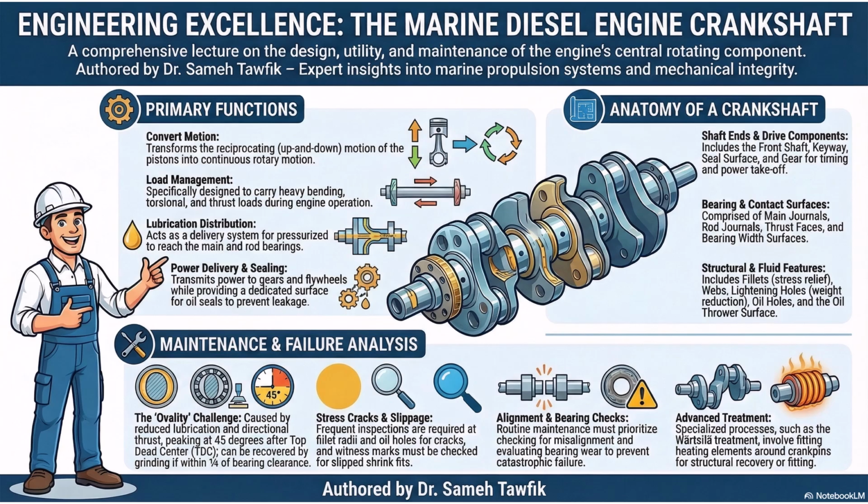Because if that delicate oil delivery system fails for even a fraction of a second, the hydrodynamic film collapses. The pressurized oil doesn't reach the main and rod bearings, metal touches metal, and the friction will weld the entire mechanism together and destroy the engine almost instantly. Exactly. It's performing brute force, high torque labor while simultaneously executing microscopic fluid management.